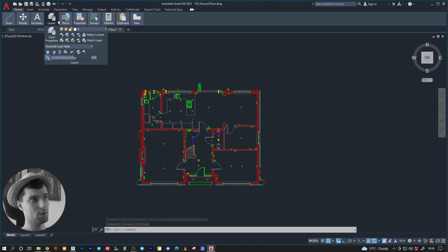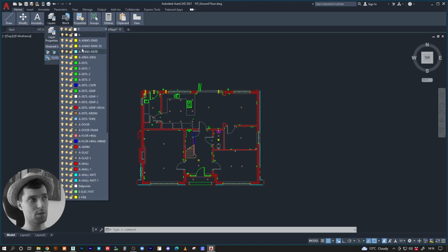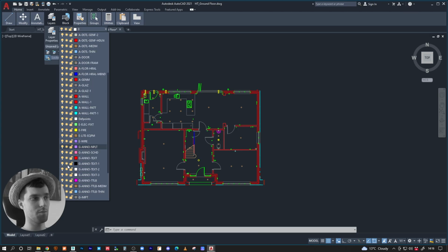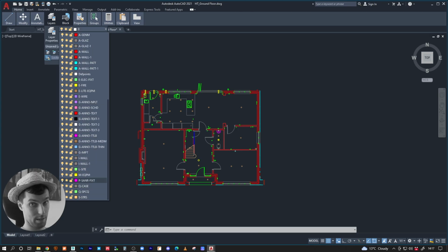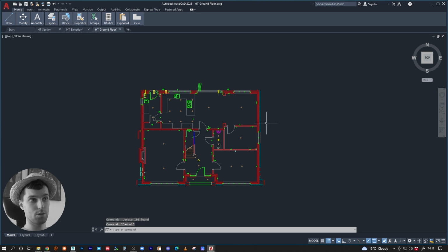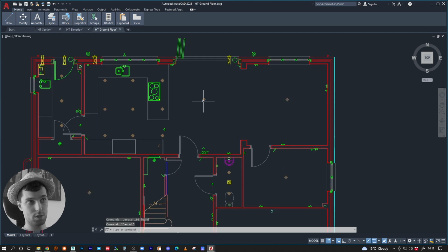So just double check, obviously, before you do that, check the layers that everything is unhidden, because some architects like to hide the layers. So for example, you're working on a drawing and you cannot see your lighting layouts, for example, pendant lights, spotlights, etc. Let's just say you write an email to an architect, your client says, I cannot see the lighting plan or whatever. And some architects are gonna reply, it's hidden, check the layers. But usually they shouldn't be hiding layers when they're sending a drawing to the CGI artist.